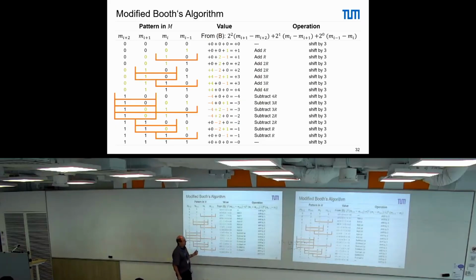So you operate, in other words, in radix 4 or radix 8. But if you operate, for instance, in radix 4, then your pre-computation becomes very simple. You need to be able to add r, 2r, minus 2r, and minus r. Minus r is just 2's complement. Minus 2r and plus 2r is just a shift of the number or of the 2's complement. So that's easy to pre-compute. We can just do this on the fly. Hardly any overhead. So that makes definitely sense.